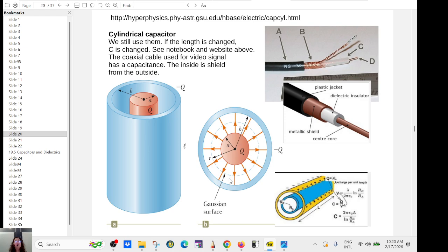So when you are doing electronics, you need to find how much charge it's going to build up. Okay, and you can do the computation and use the equation. So that will be a cylindrical capacitor. Is that clear? So we need to know those computations to know exactly how messed up our signal will be, because if you have a signal and you have this capacitance building up, it's going to slow it down. So you have to do those computations.